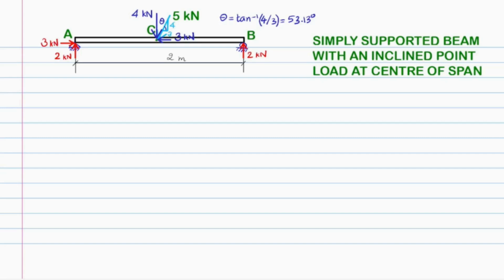At this stage, the entire beam is shown to be in complete static equilibrium with the unknown reactions found. We now shall proceed with the method of sections so that we could consider the static equilibrium of one of the parts created by virtue of an imaginary section, thus allowing us to show the resisting forces and moment developed within the beam's cross-section on the part under study and disregarding the other part created.